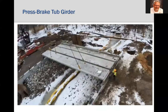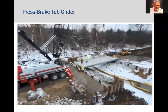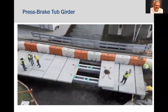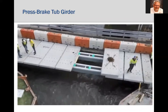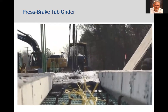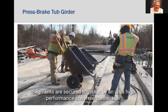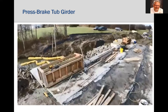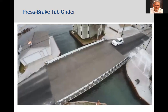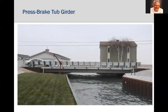The Construct system allows bridge elements to arrive fully assembled with the driving surface already installed, or be shipped in pieces for a contractor or county agency to assemble themselves. Upon placement of these bridge segments, individual units are secured together by an ultra-high-performance concrete connection. Finally, sidewalls are formed and poured on site, and guardrails are attached. The final approaches are then completed, allowing the new bridge to be put into service and the road opened.